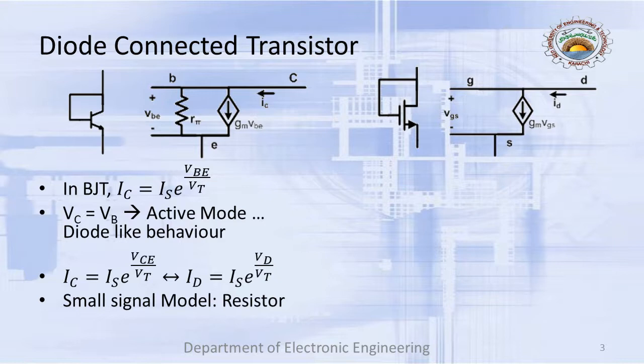Actually, when we talk about a resistor, the current through a resistor is a function of its own voltage. Whereas when we talk about a voltage dependent current source, the current through the current source is a function of a voltage at some other place in the circuit.